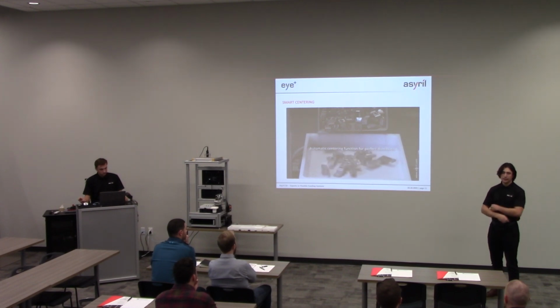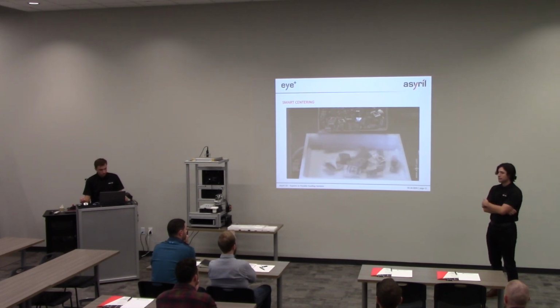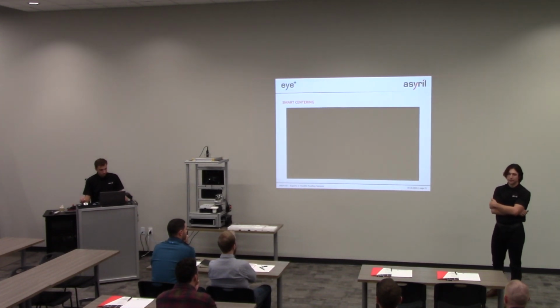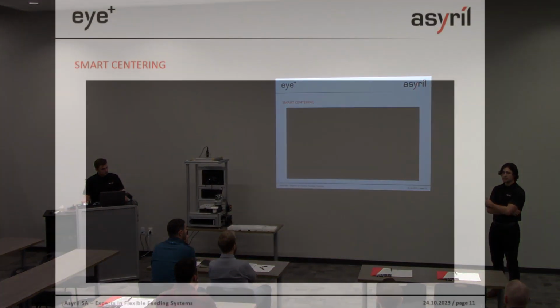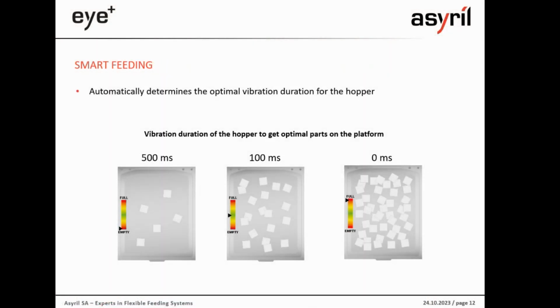Those typically are going to be robot no-go zones. And to increase your cycle rate, or make it as quick as possible, we want the parts as accessible as possible for your robot. And we found that getting them towards the center and dispersing them, that flip move, is typically the best route. Obviously, that's specific to the type of platform and application that you're on.